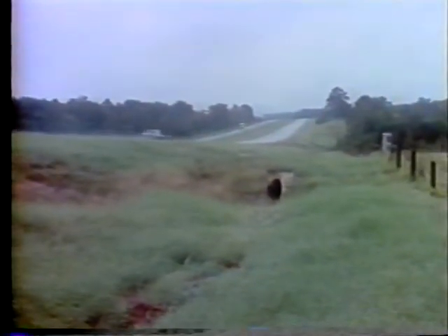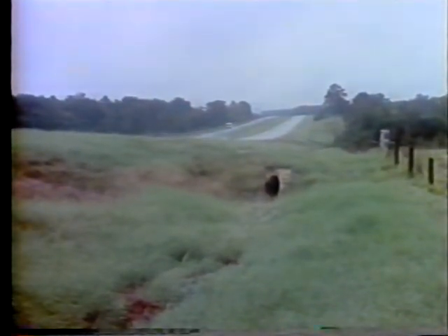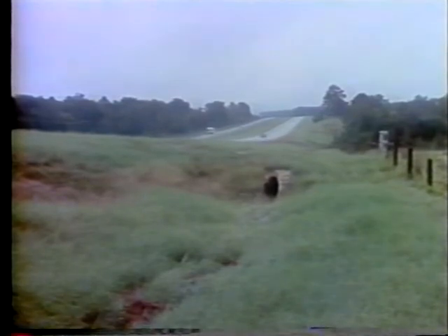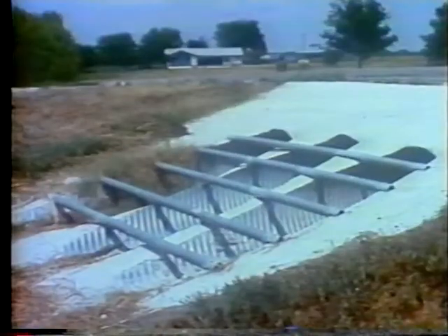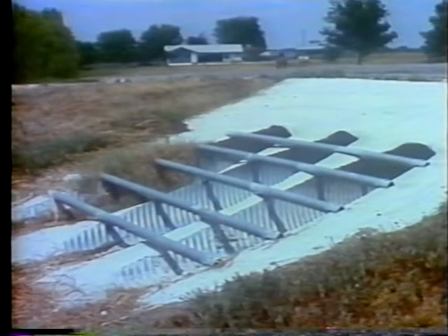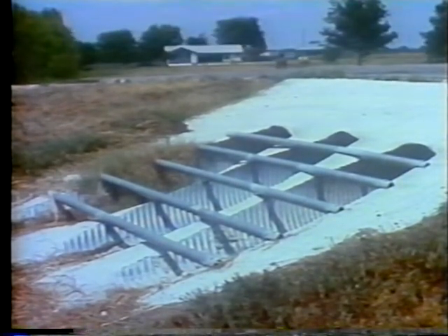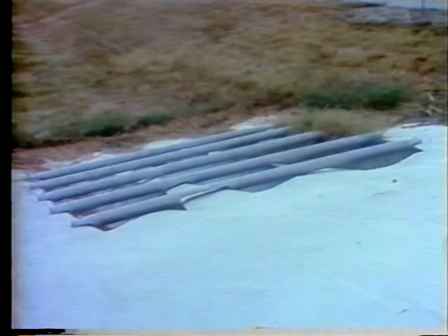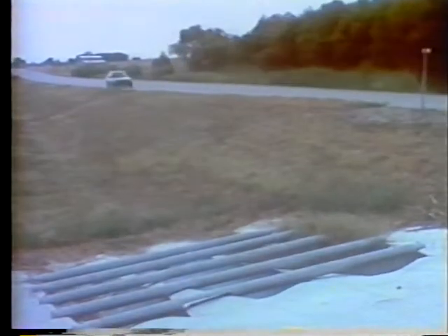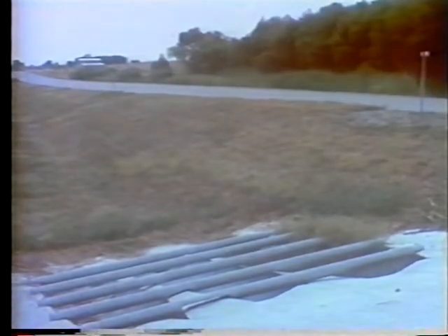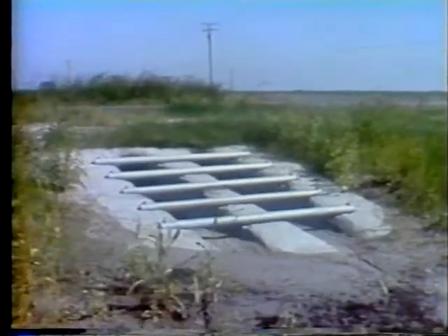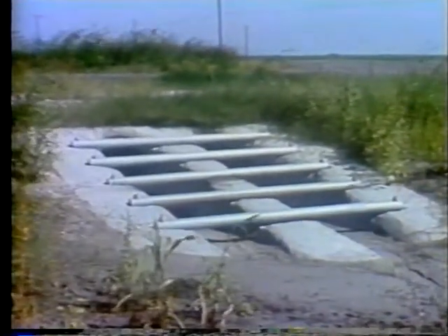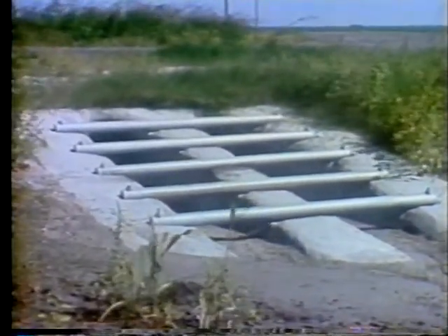Parallel drainage culverts, such as those under driveways, side roads, and median crossovers, can present a significant safety hazard because they can be struck head-on. These culvert ends should be matched to the embankment slope and have a maximum grate opening of 24 inches. The bottom bar or pipe in the safety grate should be set a maximum of 4 inches above the bottom of the culvert mouth.